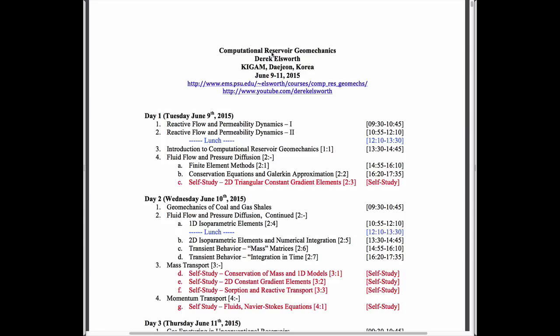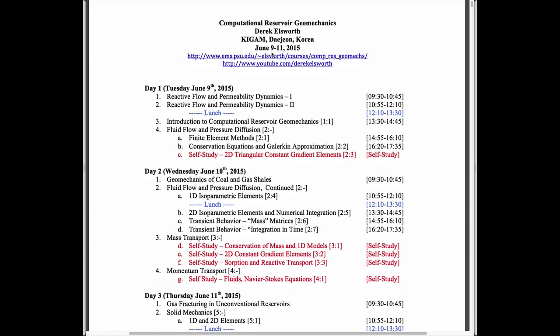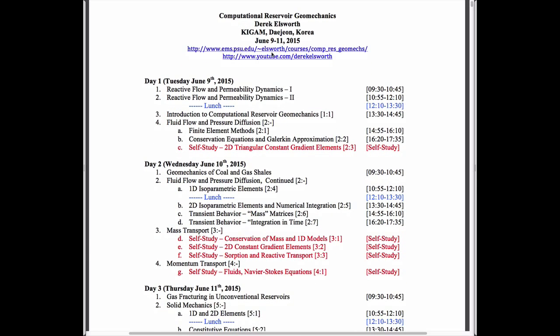We haven't covered either mass transport or Navier-Stokes equations. The Navier-Stokes equations, of course, are ones that include flow, but include also the inertial terms. And usually the difference between Navier-Stokes equations for fluids and creeping flow, if you like, in porous media, is that we assume in porous media that the viscosity of the media is included in this term for the permeability.